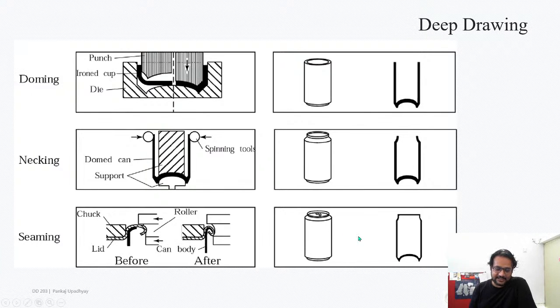Okay, let's see if there's a question. Is there a case where we use these methods for things that are not cylindrical? Mostly these two processes use cylindrical dies, or somehow the parts have cylindrical symmetry. The reason is that if there are corners, then it becomes very difficult for us to manage the flow of material in such intricate shapes, okay.